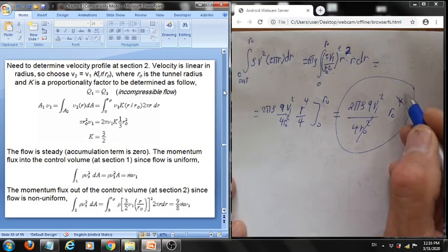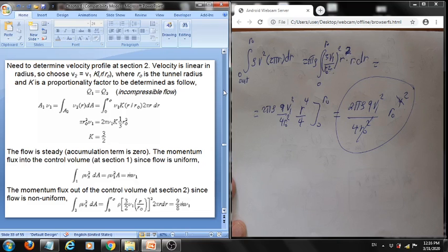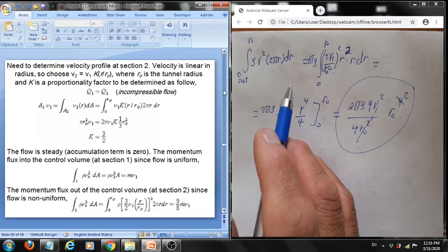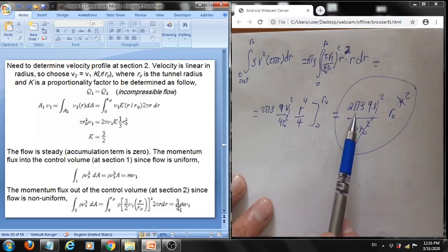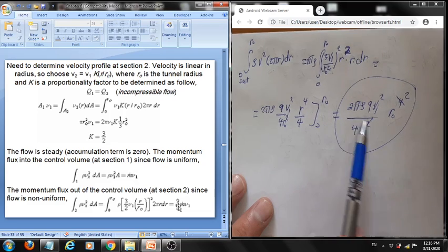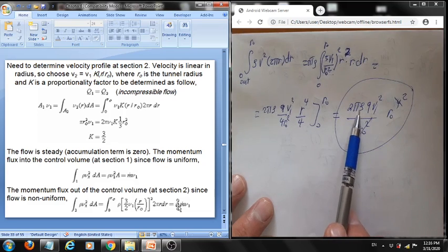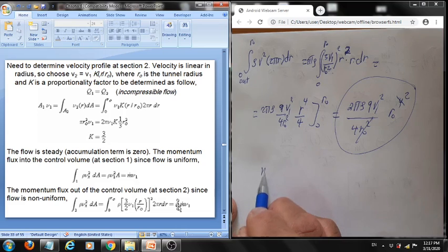Obviously we can cancel, it becomes as seen here, and then we substitute these into the momentum equation to find the drag. Okay. Here he puts it in a simple form, which equals this. We can see this by recognizing that the area is pi r squared, the density times velocity times area is equal to mass flow rate.